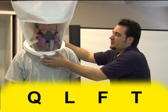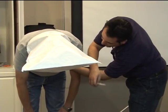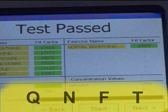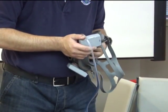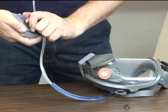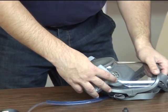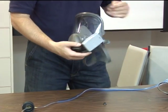Qualitative fit testing is accomplished by temporarily converting the respirator user's actual facepiece into a negative pressure respirator. The quantitative test, often referred to as QNFT, uses measuring instruments to measure face seal leakage. Quantitative fit testing is accomplished by modifying the facepiece to allow sampling inside the facepiece in the breathing zone of the user, midway between the nose and mouth. Any modifications to the respirator facepiece for fit testing must be completely removed and the facepiece restored to the NIOSH-approved configuration before the facepiece can be used.